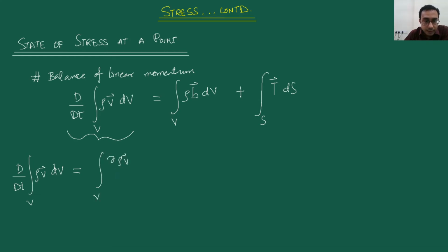we'll write it like this: the del t of rho v dV plus the rho v term again. Okay, this rho v is the same rho v as here, but now this surface term. Okay, now we don't want to keep it in the form of a surface term. So you understand that we are writing from here to here using the Reynolds transport theorem. Okay.